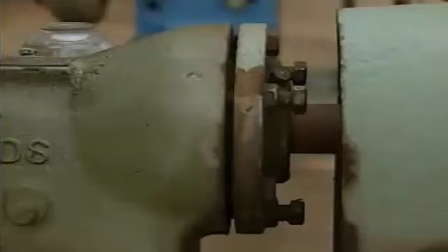All sliding surface bearings are subject to load and vibration, which cause the metal in the bearing to flex and bend. The metal is gradually weakened by the flexing and bending, and eventually the bearing fails. The bearing surface then breaks up and becomes rough. This roughened surface causes an increase in the bearing's operating temperature and an increase in vibration.